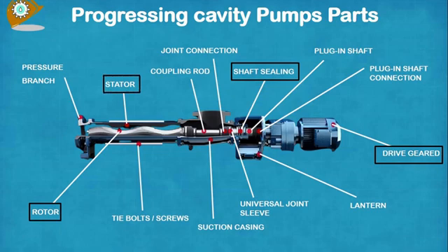The stator of the pump is designed and built in single block design. It is composed of a steel shell, which has a double helix profile inside made of rubber. The main elastomer types used in stator manufacturing are nitrile butadiene rubber, ethylene propylene diene monomer rubber, fluorocarbon, and polytetrafluoroethylene, chosen in function of the abrasive media, chemically aggressive fluids, and various working temperatures. The second component is the rotor.